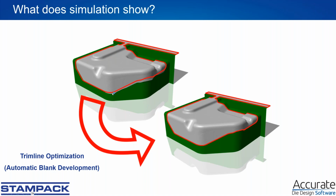So here the user imports a target part. You see it here in red, and in the first iteration you see here is too much material, and here is not enough material. So here we have to add material to the initial blank. Here we have to remove material from the initial blank. And what Trim Optimizer does, in a fully automated cycle, in several iterations, it optimizes from here until you are perfectly in tolerance.